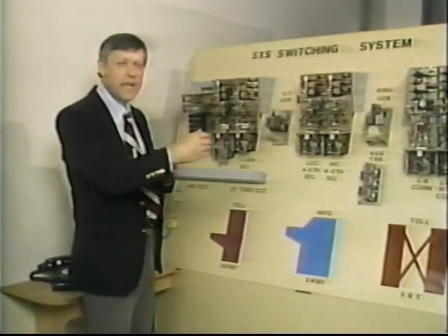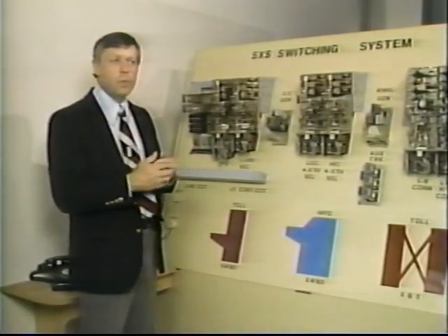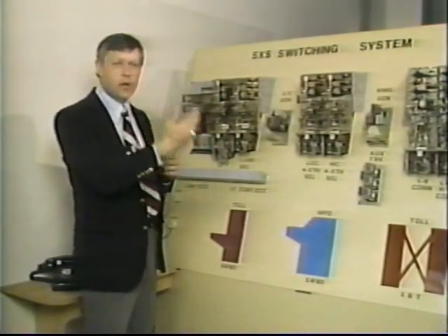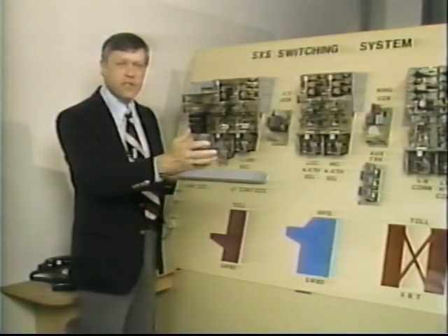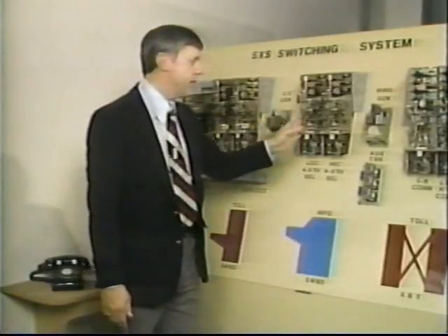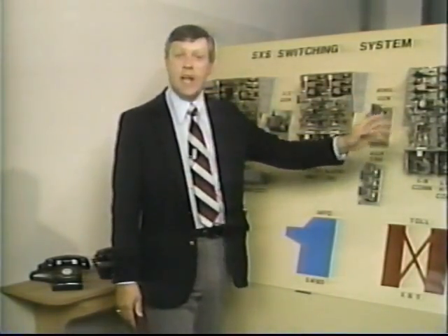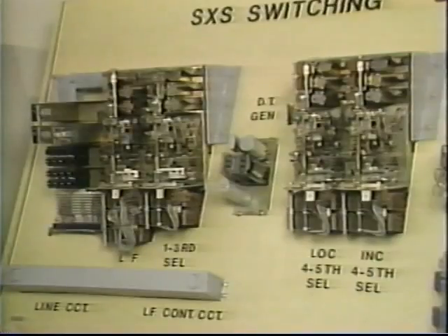There are only so many registers, as they call them, that can take a dialed call. So when you go off hook, the line finder finds your phone and feeds dial tone to it. Then as you dial, you'll see the call progress down digit by digit until a telephone rings at the other end of the dialed call. Now the first function you're going to see is when the telephone goes off hook, the line finder will seek it and give dial tone to the caller.